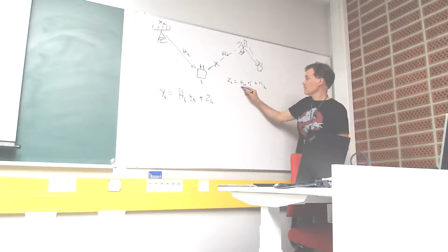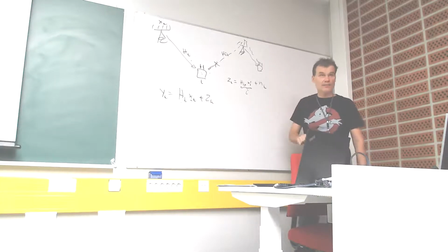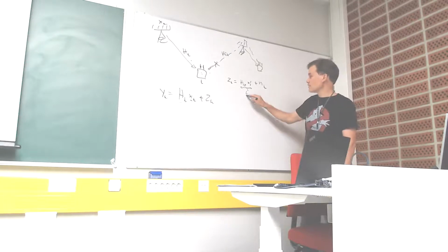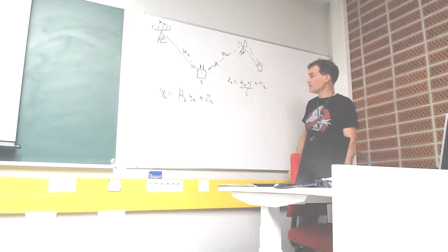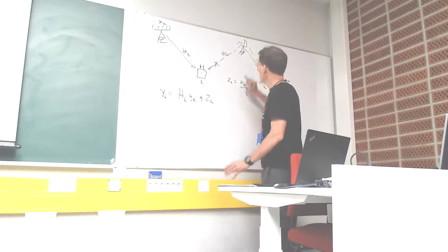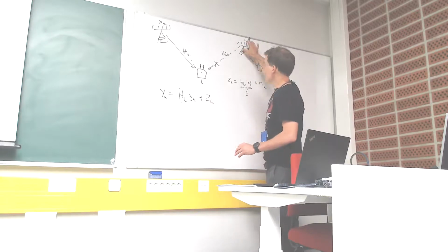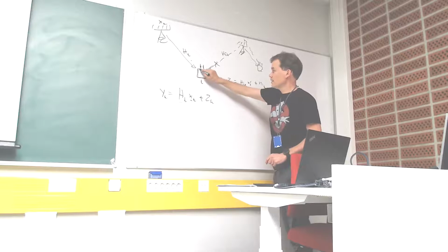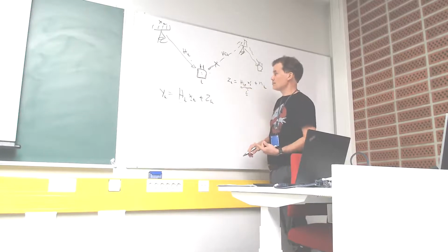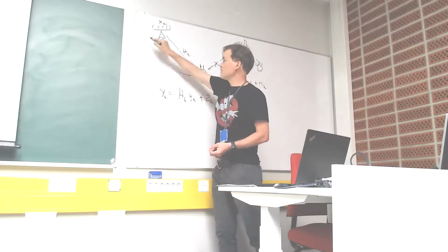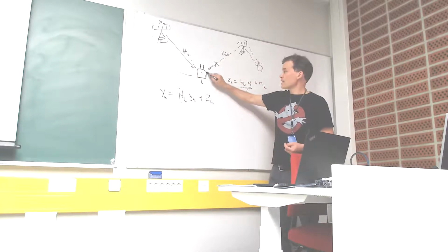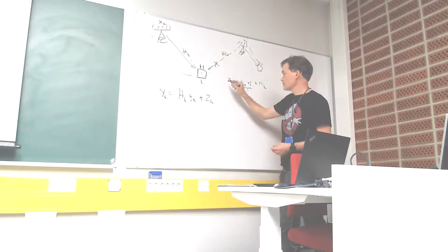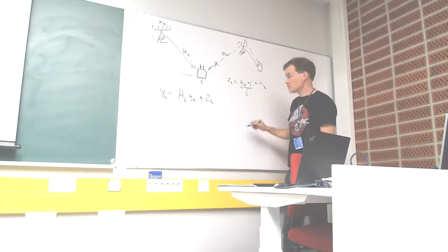Or we can call this simply a vector I, the vector I that is caused by the interference at this user K, right? But we don't know about it. The system has some knowledge somehow, maybe via explicit feedback. The base station knows the covariance matrix. So the user can actually estimate the covariance matrix of the noise process, right?